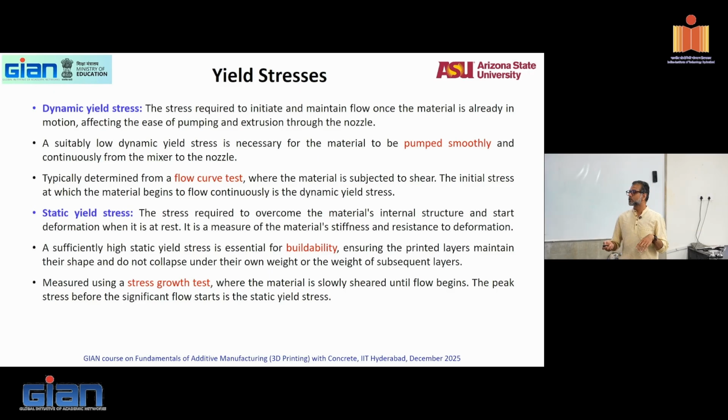Constant shear rate. Okay. So you did a constant shear rate. You did a static yield stress, which is a good indicator of how much buildability you can get. The dynamic yield stress that you do on a strain rate growth test, for example, if you build up from a strain rate of 5 to 100 and you take the up or down ramp and take the slope, when you get the dynamic yield stress,